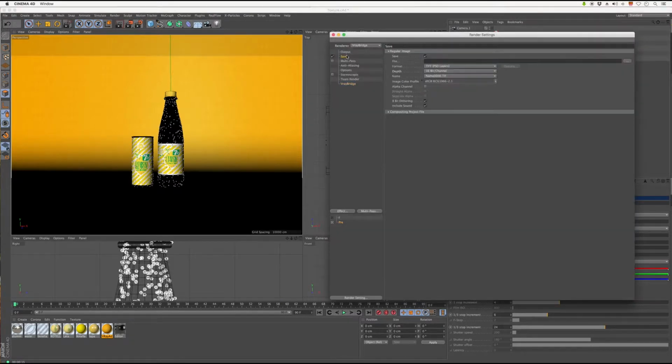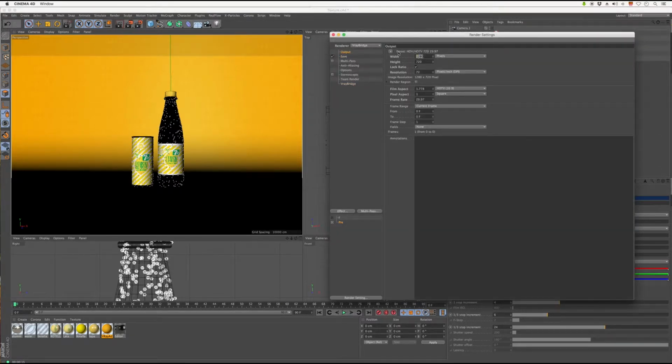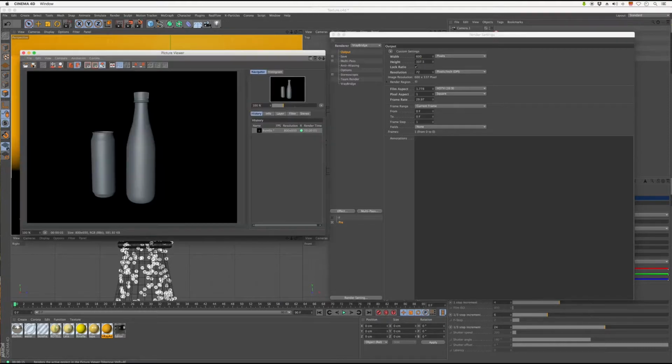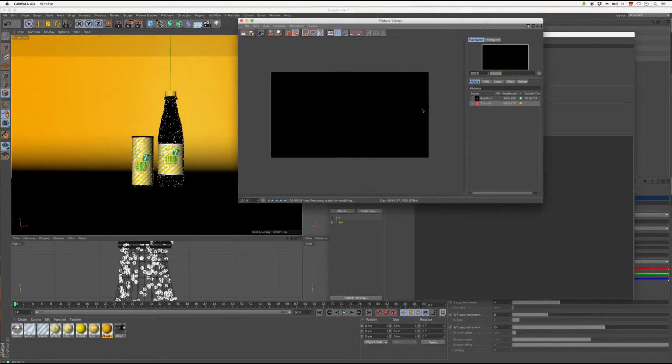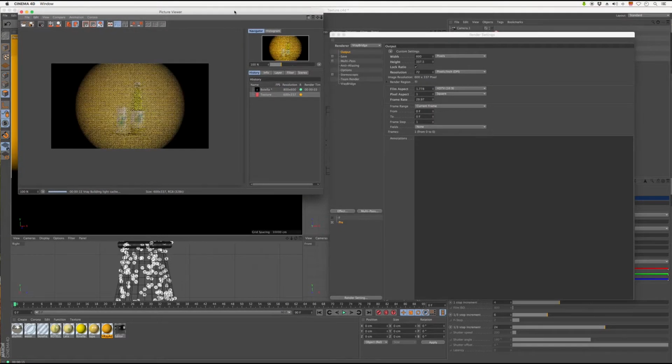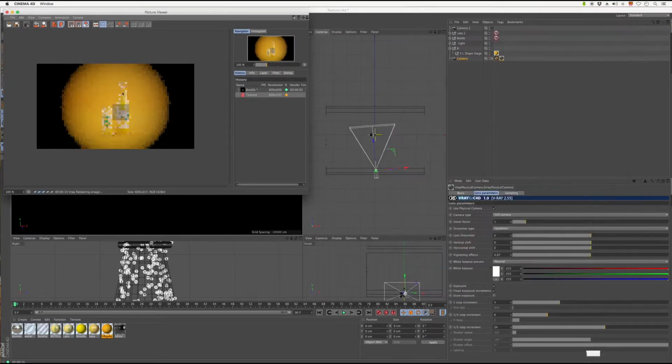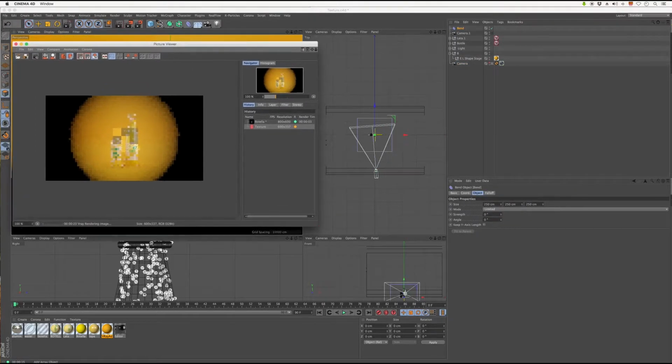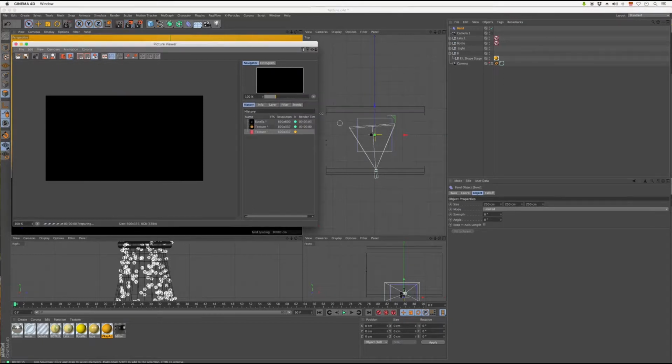Then we could try a preview render. So let's adjust the settings here. We could put a width of 600. Uncheck save. Let's take a look to get an approximate idea of what the final render will look like. So the vignetting effect is way too much. We can go back to the options and lower it, maybe to 2. Let's take another look.